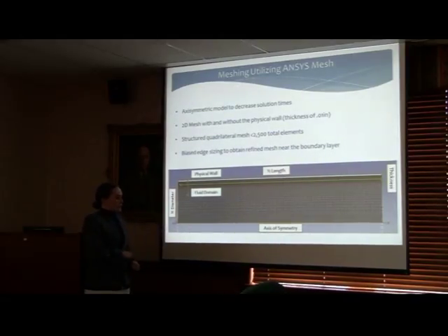And the reason that we did 2D is the way that we modeled it in Fluent was an axisymmetric model, so that's our axis of symmetry, and it's going to rotate all the way around, thus basically solving a 3-dimensional model of the pulse tube. But with way less time, so it's going to take far less computational hours.